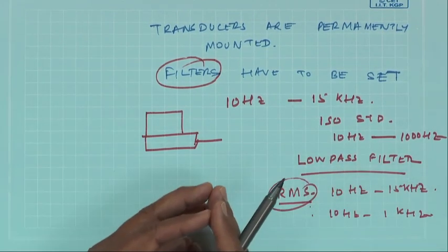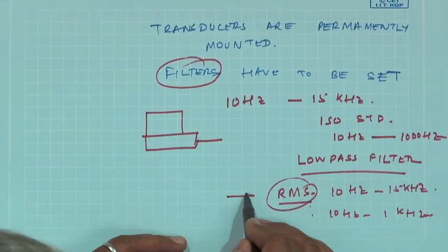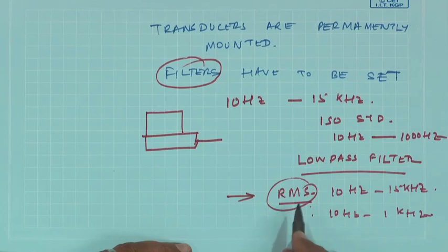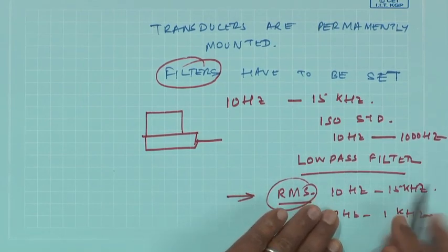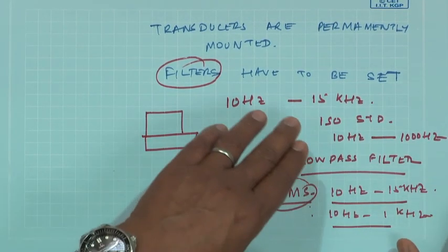Then we take it for granted while we are doing measurements that whatever transducer is there, we just get an output and see that this is what it is. It is exactly not, because in CBM we will be dealing with signals which are dynamic in nature, signals which change with time. So, there is a strong frequency component in those signals. So, one has to be careful that what are the signal features we are measuring, we are in the frequency range of measurements which we are interested in. Okay. That has to be done.